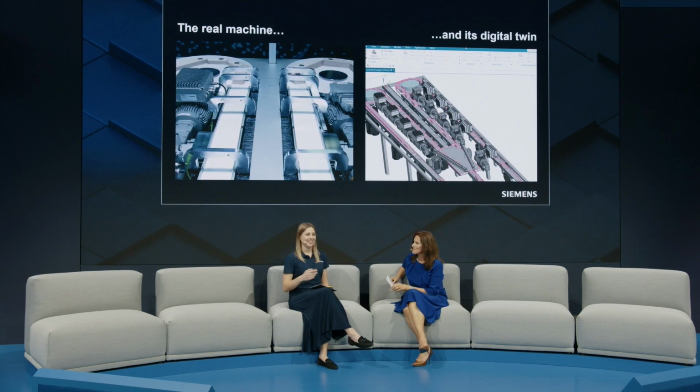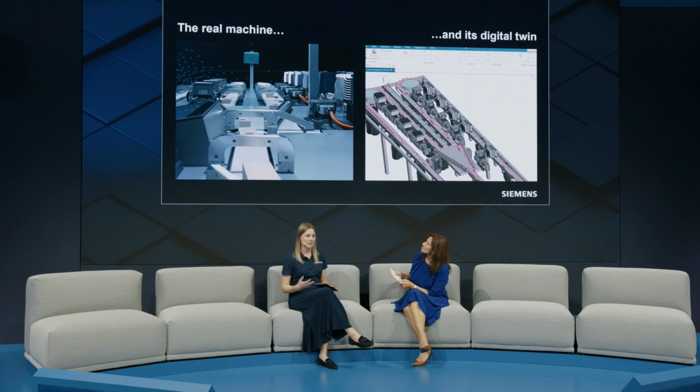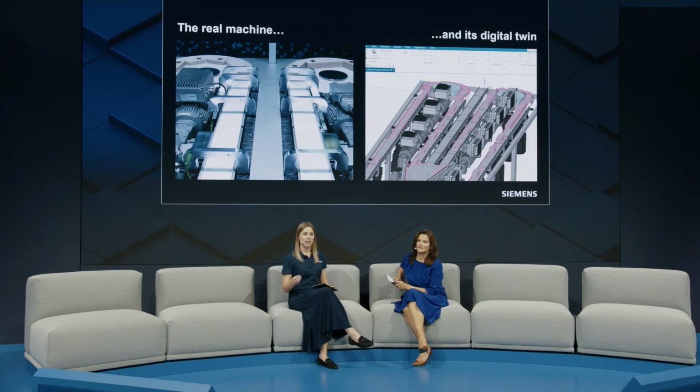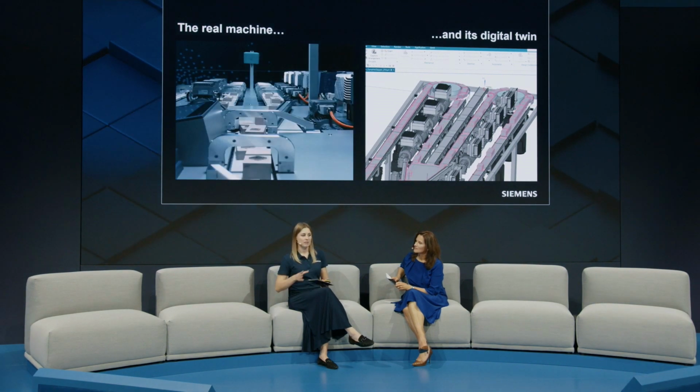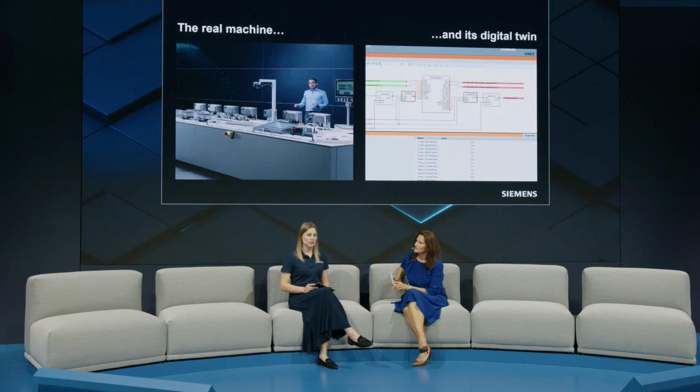Right. So, you have two in-feed conveyors, and there are parcels on there in various sizes, and they're supposed to be there in a certain distance. Then they're supposed to be combined on one outfeed conveyor with a defined distance. The size we can calculate with the sensor and the motor data, while the distance we can calculate with the dynamic changes of the conveyor belt. The goal, of course, is to keep the distances between the parcels according to the requirements, while maximizing the throughput. With simulation, we were able to reach this goal.